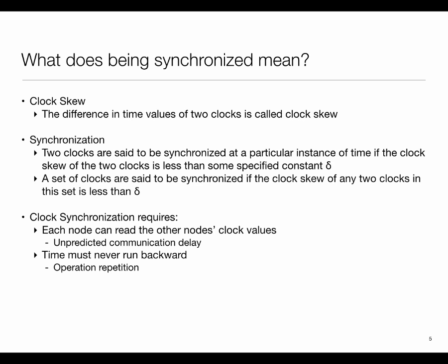So we talked about imperfections in frequency, instability and all. But imperfection in time refers to the fact that my counter is reporting a value which, when I map it to my notion of time, does not correspond to whatever my coordinate system is. I think I'm at 1 p.m. on November 20th, but maybe the actual time is 2 p.m. on November 20th. And that difference is what is called the skew.